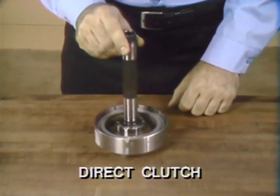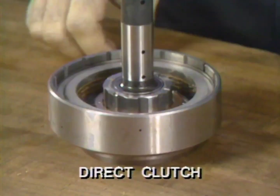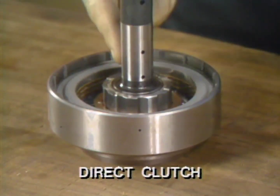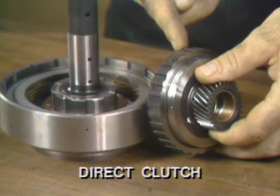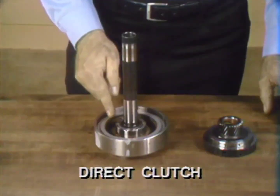The direct clutch is used to bypass the freewheeling feature of the one-way clutch. The plates are installed in a rotating cylinder which is integral with the turbine shaft and the one-way clutch inner race. And the sun gear outer race assembly has external splines that mate with the internally splined friction clutch plates.